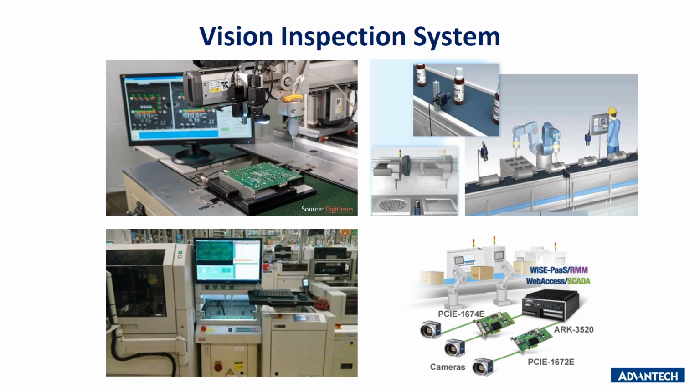AOI, automated optical inspection, is to replace human eyes to do the quality detection of the production. It includes the motor control, CCD or CMOS camera, light, and lens. This AOI machine normally uses a PC-based control inside to help do the optical inspection. The process will check the item position, take pictures, do image analysis, and feed back the result to the machine, doing actions such as passing good items or picking up failed items, then record the picture and counting to the data manufacturing center. It's another example of an automatic machine.